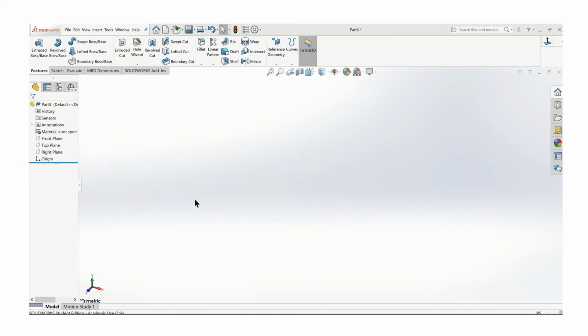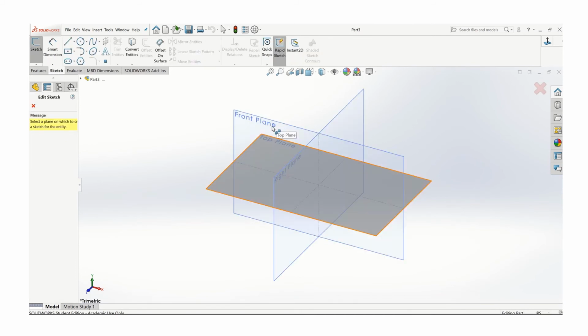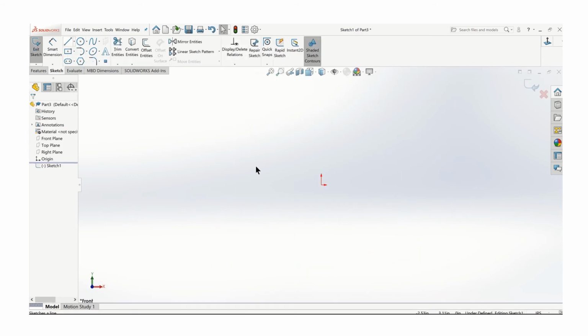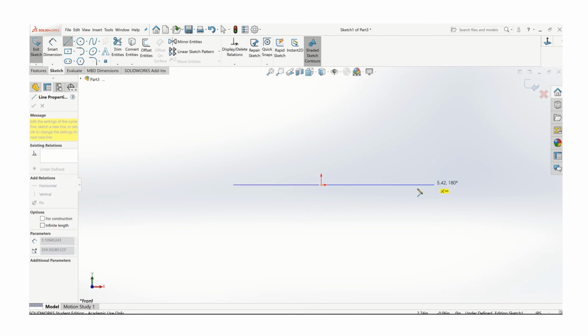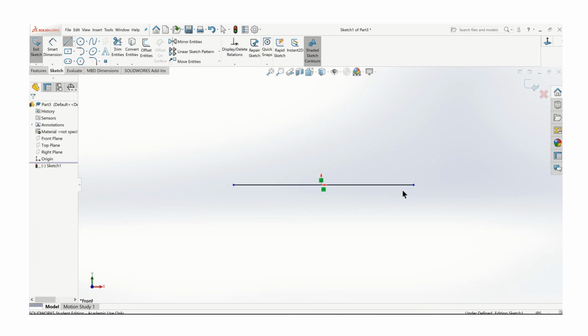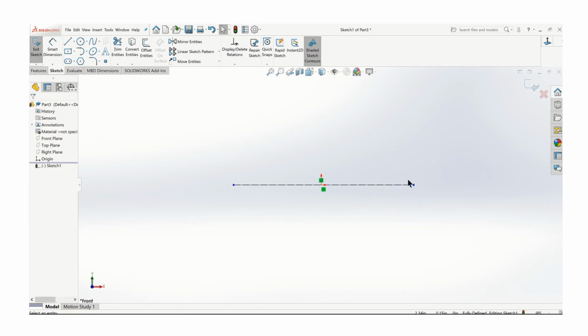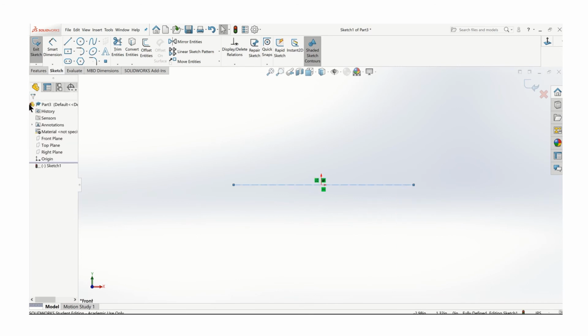Now also, if you have to make something like a sphere, if you've ever had to do that, how do you generate a sphere using a 3D model? So I'll do the same thing. I'll create an axis. Oops, I get my line tool. Now you have to turn that into a construction line, otherwise the software will think that's part of your object. And again, I'll fix that on there.